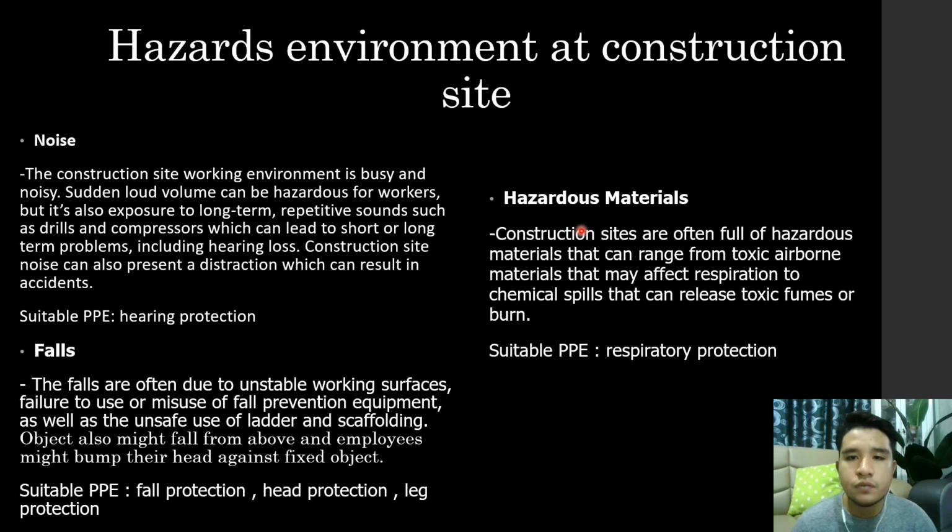And the last one is hazardous material. Construction sites are often full of hazardous material that can range from toxic airborne material that may affect respiration to chemical spills that can release toxic fumes or burns. And the suitable PPE for this hazard is respiratory protection.